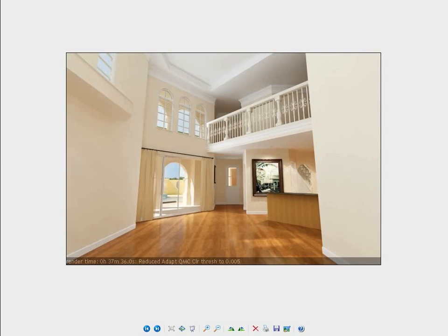I'm sure that if I increase the image sampler settings, if I increase the min and max value, if I increase the radiance map resolution, maybe add some detail enhancement, which I would only do as a last resort, maybe if I increase the light cache subdivision value, I could get all this detail to show up in the molding. But instead of enduring some really long render times, maybe 2 or 3 times the amount that I have right now, I'm just not willing to pay that price, and I want to leave it as is.